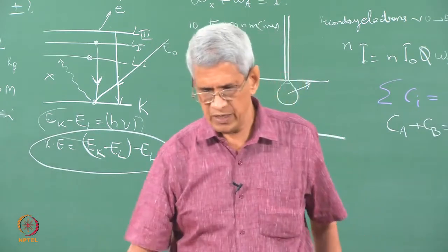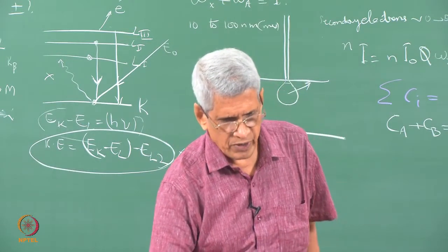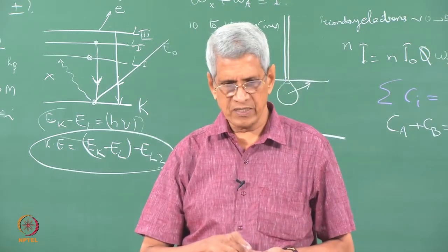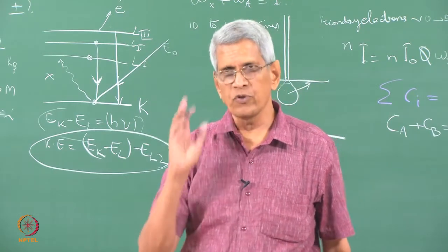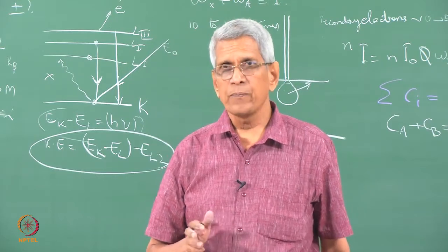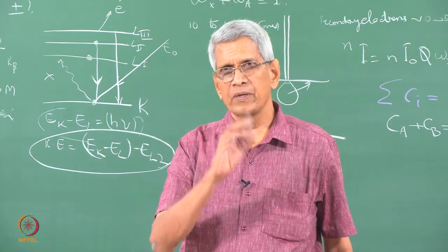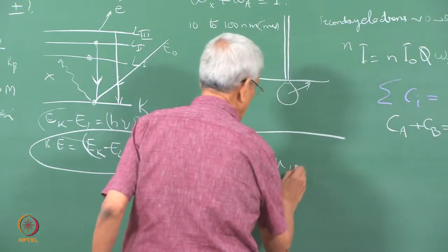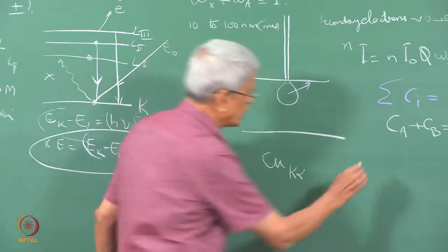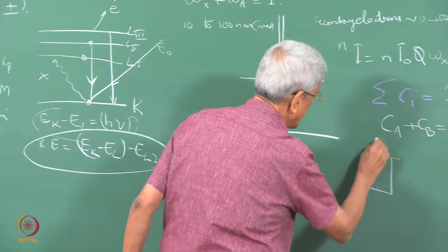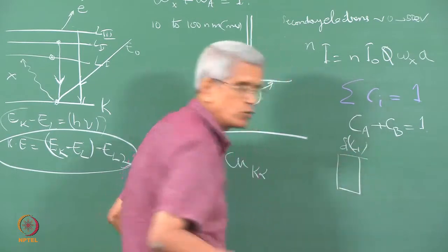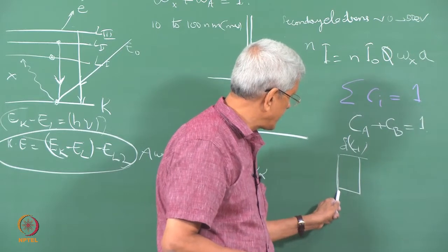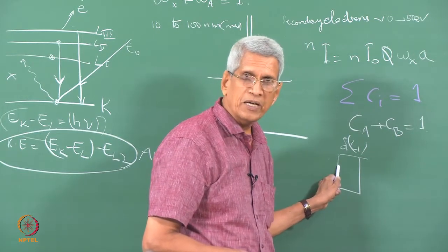Okay. For which, what are the things which can come? One, an escape peak. Escape peak is what it is called; it appears due to fluorescence in the detector. Okay. That is, as the X-ray beam with a particular energy, suppose we assume an X-ray from copper K alpha is entering into a detector. The detector is nothing but a silicon detector which is normally used. Okay. As it enters, initially there is a region called a dead layer where no information is being collected.